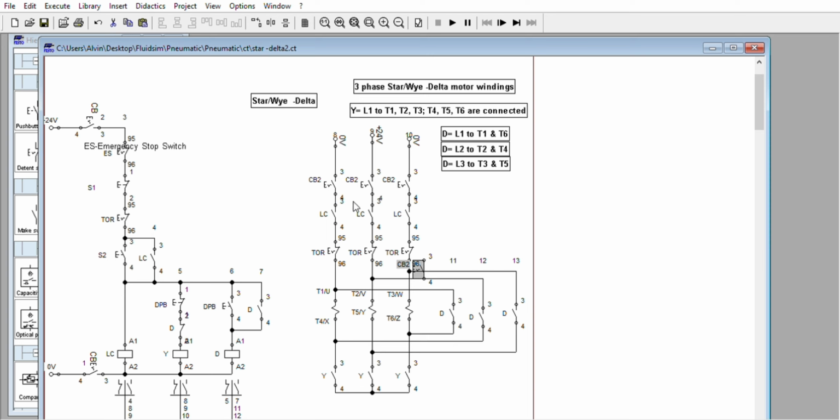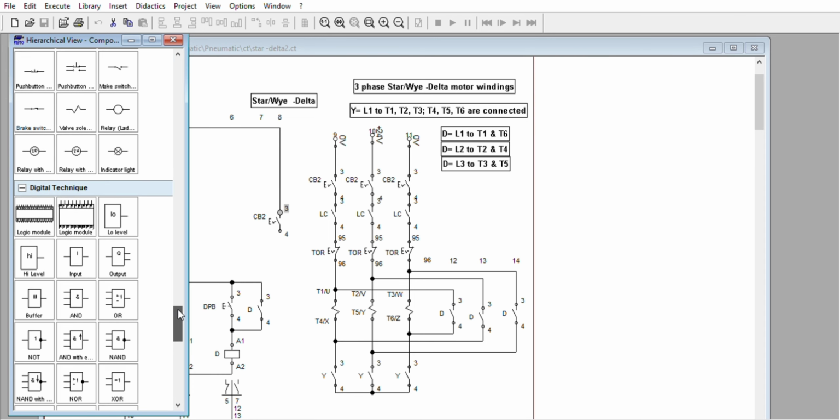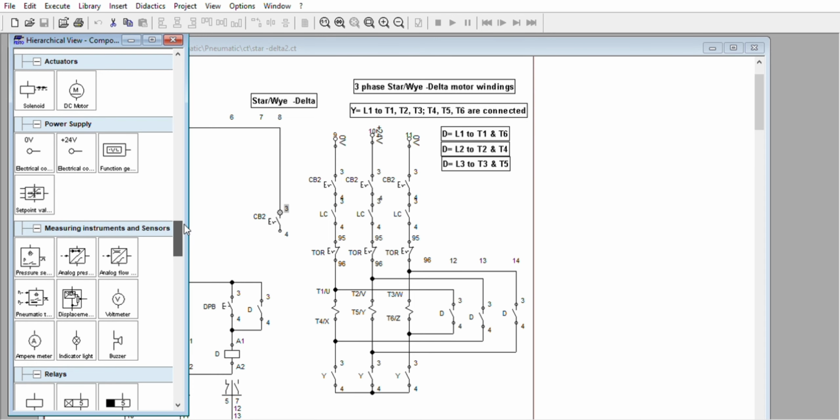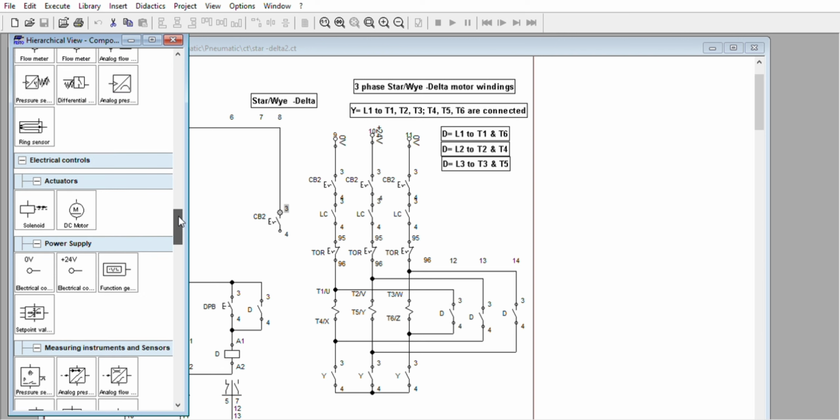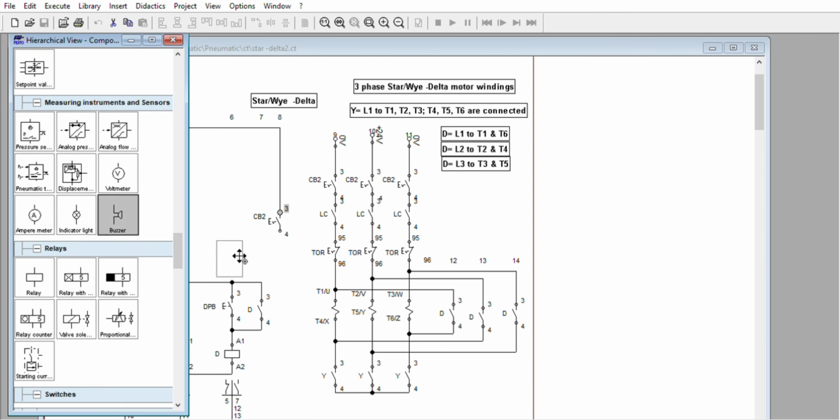So we are only simulating the overload relay using only the normally closed detent push button. Connect here. It should be directly connected to the circuit breaker. Refer to the previous videos for why it is directly connected. The normally closed push button must not control the alarm.